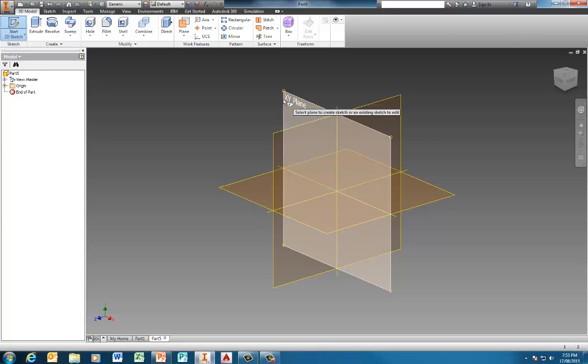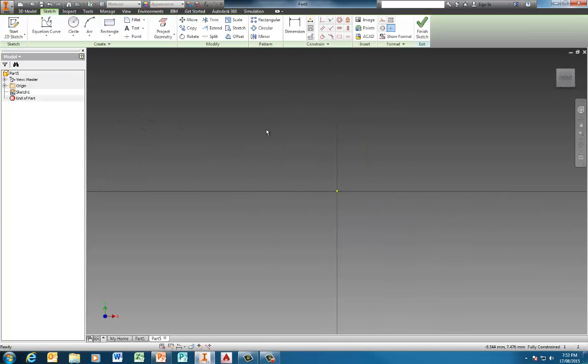So selecting our very first plane, we need to firstly create the base, and I'll do that using the rectangle command, and once again I'll shortcut creating the various dimensions and constraints by snapping to the origin point for the first point of my rectangle and then typing in the 80mm width, tab, and then the 50mm height of my first rectangle, and you'll see that that is then created already fully constrained.